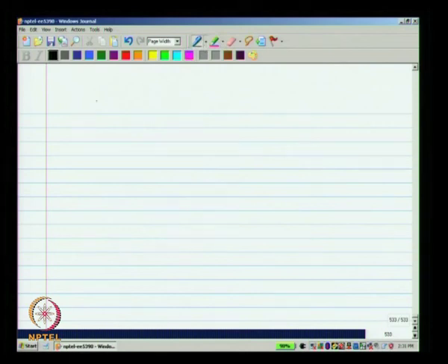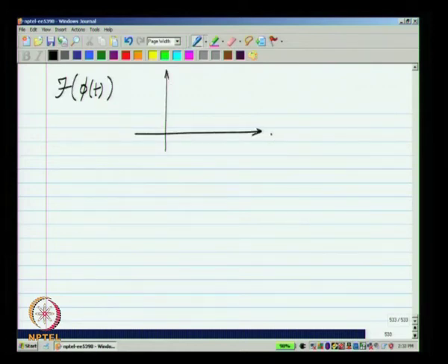As long as you understand that f naught means average frequency, this f of t means instantaneous frequency, and these time varying parts can have their own frequency, everything should be fine. And it is also quite common to sometimes take the Fourier transform of phi of t and plot it on some frequency axis, and it could have any kind of shape. That is basically phi of f. So, this frequency axis denotes the frequency of this phi of f, that is, this phi of f denotes the content of phi of t at different frequencies.